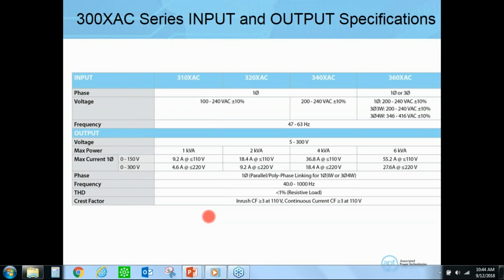So again, if you knew your voltage for your product, let's say 100 volts is the requirement, or 120 volts, your US standard voltage, and I need to have a 4 amp current draw. So 120 times 4 will give you 480 watts or VA. So 480 is what's required. A 1 kVA power supply is almost double the power, and this is enough to drive the load that you need.